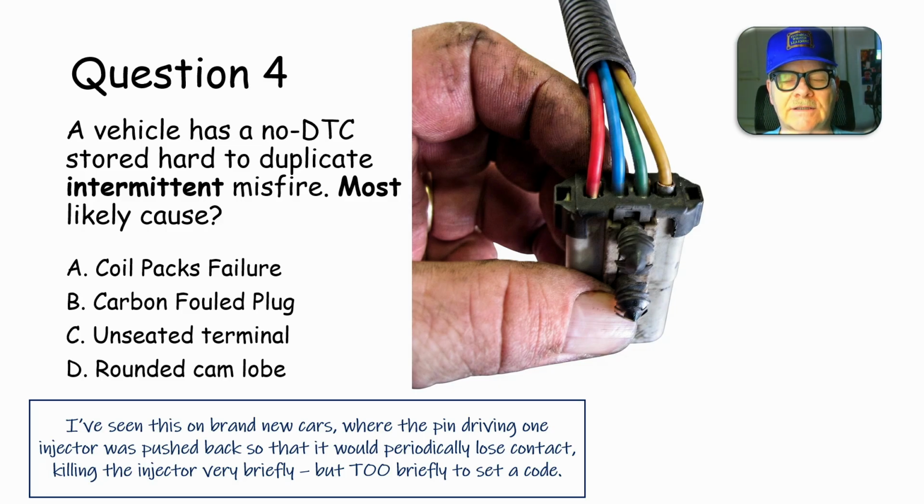And so they brought it over there, and I never really felt it do that, but I just started looking around, and I noticed the crank sensor. The standard colors for crank sensor wiring for Ford, even way back then, was blue and gray. The crank sensor connector had a pushback terminal so that it was barely touching. And that was the reason that it was doing that. Now, what about this 5-minute timeout? I don't know. But when I pushed it in there and got that thing seated, they never had that problem again. And I'm telling you, pushback terminals that are just barely touching will do crazy stuff because of temperature changes and all kinds of other things. Engine torque and, blah, blah.